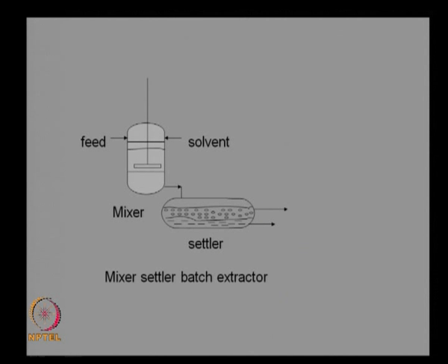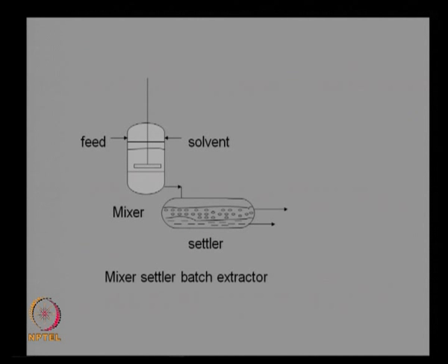But there is always, as I said, non-ideality comes into picture. So the interface between the two layers may have some solids which has precipitated out, it may have a combination of both these phases, you may have the little bit miscible solvent into the heavies. So the middle portion will not be very sharp, there could be another layer which needs to be disposed of. This is a batch operation. You can have several types of continuous operations.